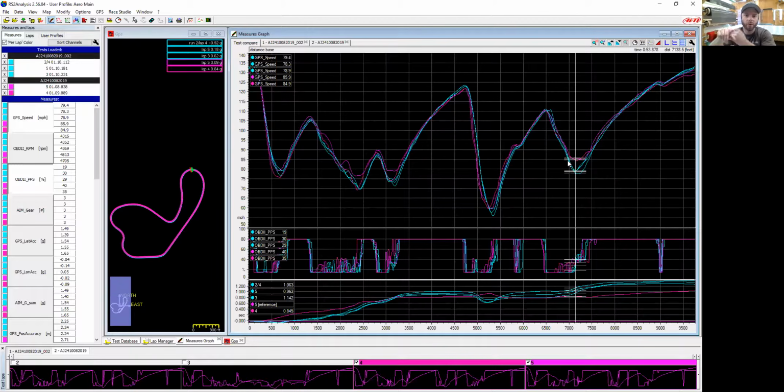Looking at the dates on these, these were the ones where I de-aeroed the car, and I did a whole video on this. So the red runs were in the morning, and then during lunch, I swapped the large ST2 wing and splitter for my American Iron wing and splitter. So an hour and a half later was the blue runs. And I think I kept it in the video. The first time I went out with the American Iron Aero, going into turn 2, I went too quick. Didn't have as much grip as I was expecting. Yeah, and down where Roger's pointing, if you look at my GPS trace, it goes way off a little bit. I decided not to include that lap in here.